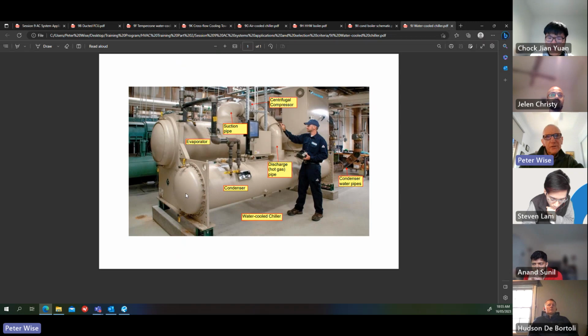Sometimes they'll have cathodic protection on these ends. They're called water boxes, okay? Water boxes is a common term. Or you might want to look at the materials of the water box and choose a different material which has good corrosion protection, such as stainless steel. Obviously, they cost more, but you can get them. Also, the tube sheets inside can be different materials. The tube sheets support the tubes as they go through. You can get those in different materials as well.